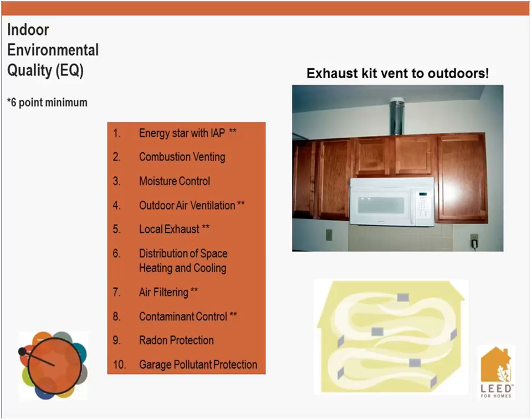We're going to be looking at what you might be doing in the house as far as contaminant control. So encouraging people to take their shoes off when they walk in, to not bring that in, all the way to sealing the ducts during construction or ventilating the house after construction to get the VOCs out. Radon mitigation systems, putting a pipe down in the basement and running up to the house is required in zone 1, I believe, the worst zone. It's extra points in zone 2.